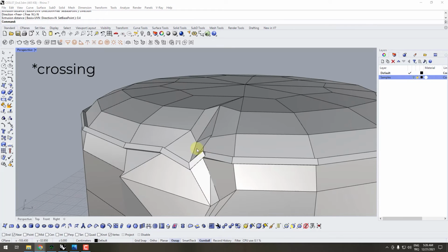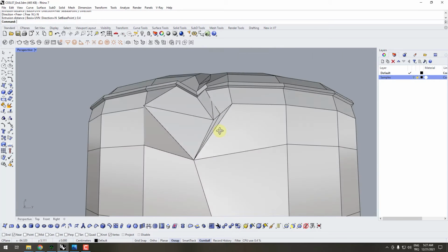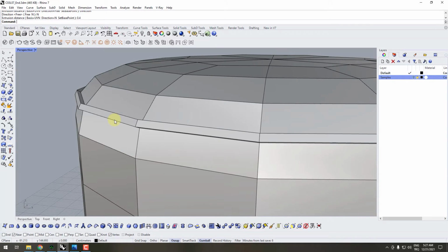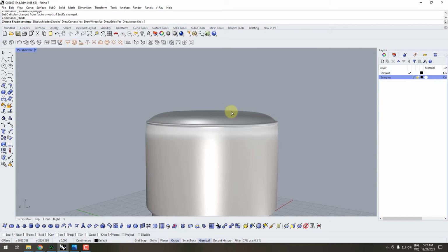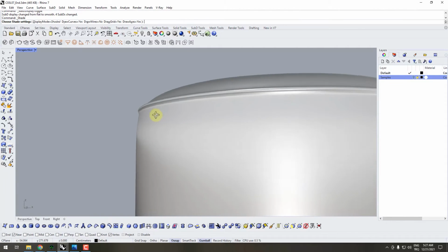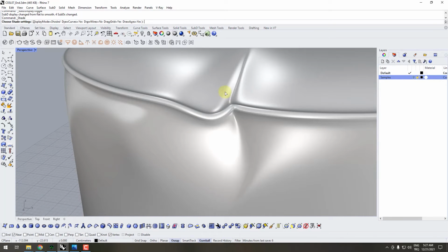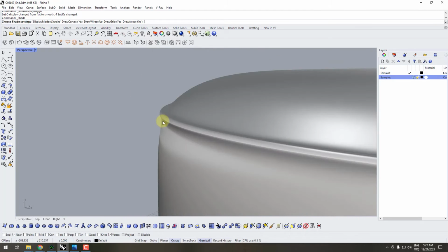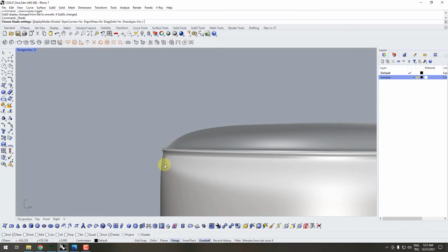There are some concentric faces here, but in SubD modeling and at the current level of our course, that's not a problem for us. We have created our extrusion, and when I turn to the SubD state, you can see that we have a nice piping detail, and it wrinkles through the wrinkled area too. Nice. If you look closely, you can see the bottom side of the piping is smoothing to the side surfaces.